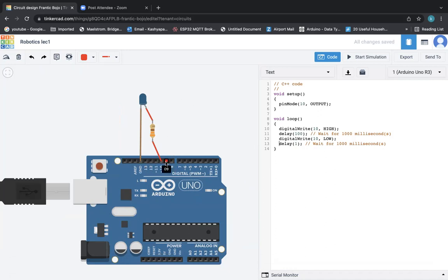When you are using two LEDs, you will use two different pins to power up the LEDs, but then you have to connect your LEDs to the ground. You can use the same ground, or else you can use the two grounds on this side as well. Is that clear? If you have free time, try to add another LED. If you want to add three or four, just go ahead. If you really try, you may be able to come up with very nice patterns as well. Is that all clear for you?